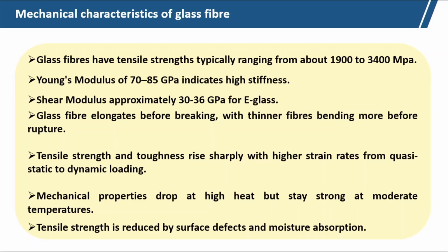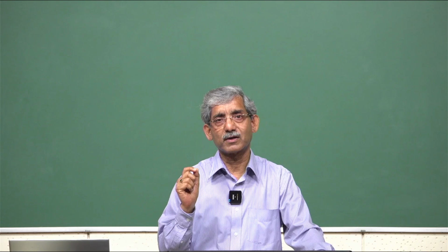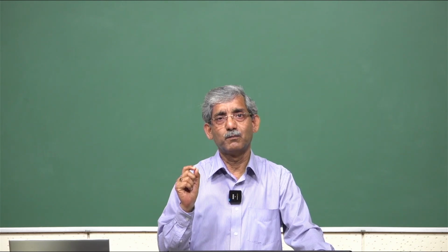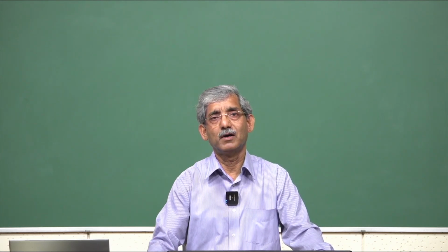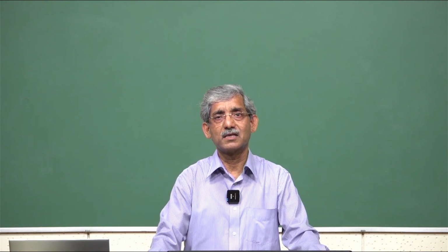Tensile strength is reduced by surface defects and moisture absorption. That is true for any fibers. So, in glass fiber, in case of any small surface defects or some porous portion, in that case the tensile strength drops.